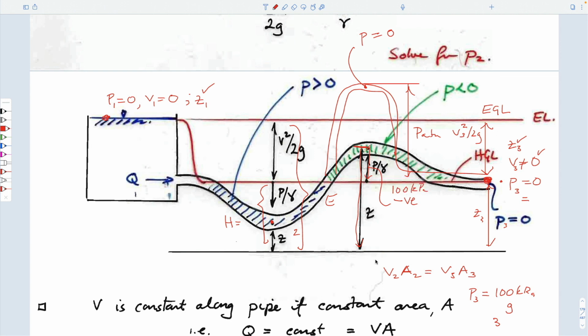So if you want to de-air water for experiments in the lab, take the dissolved air out of your system, then what you can do is get 60 feet of Tygon tube and run it up 3 stories, right? 1 story is 10 feet, roughly, and then make a siphon. Put it in some water, suck very hard to get it to go, or actually easier, just fill it, take the middle point of it up 3 stories with your thumbs across it, and then you have it filled so it goes up. You put it into a beaker at this end, slightly below the level at this end, there's a siphon, and then you have the water go up through this.